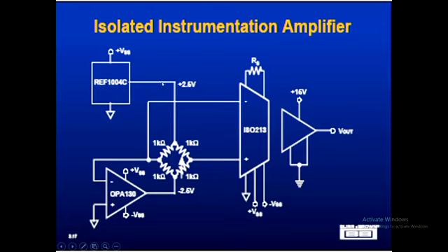This device here is meant to provide a reference voltage from some supply that might vary a bit. So it's meant to have a regulated output of 2.5 volts. Why would this be minus 2.5 volts? Is it because of the virtual ground? Perfect. Well done. It all comes back to that virtual ground business, doesn't it?